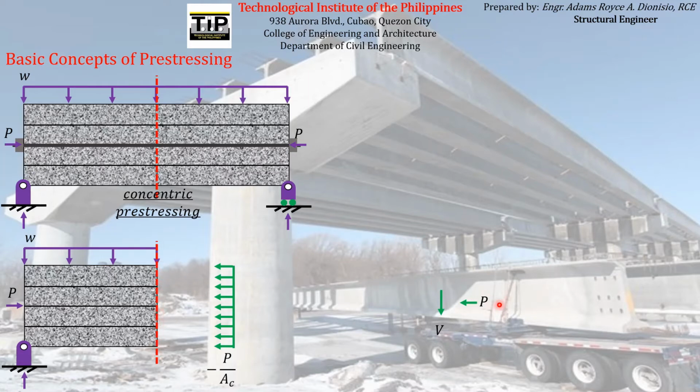So again, I just moved the drawing from this part to this part just to have an open space here. Along with the shear force, another thing that is being produced due to the application of this uniformly distributed load is what we call bending moment. Although again, may I just reiterate that this shear force is actually the resultant of these shear stresses acting along the cross-sectional area.